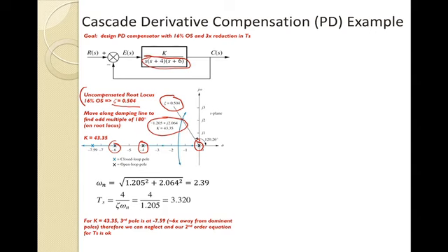So from that point, with the values of the pole locations, what we can do is find omega n. I want to draw a quick reminder in the complex plane. For a pole location, for example, if that's our pole location, we know where the real and imaginary parts are. The real part, we call sigma, and that is going to be negative the damping times the natural frequency.